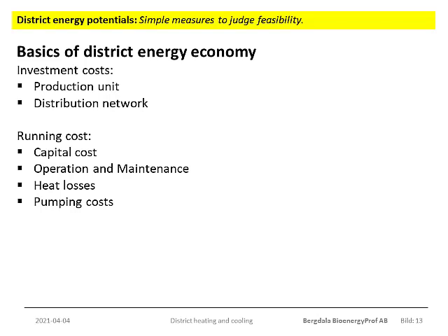Second, you must consider how you want to start. It is quite possible to build a system step by step. So you build a small local network first and make that run. And then you build a new one. And after some years, you start connecting the small networks to each other. And then, maybe, the system is large enough to accommodate not only heat production, but also electricity and cooling production. Or, of course, the other way around. Not only cooling production, but also heat and electricity production.